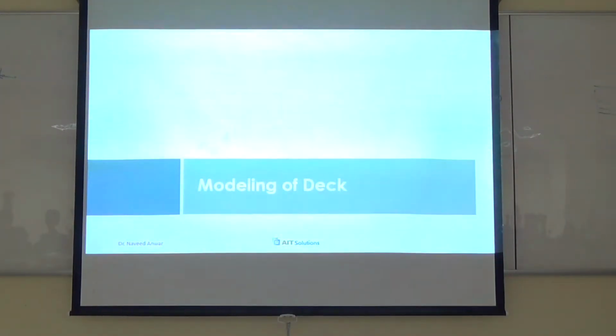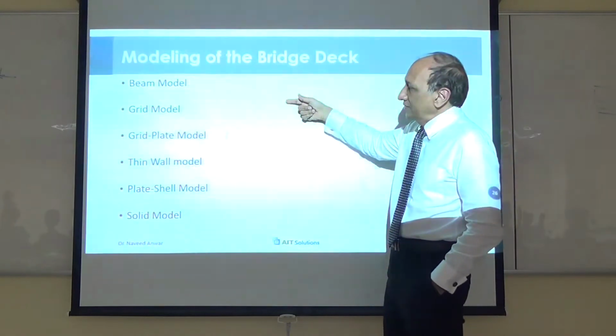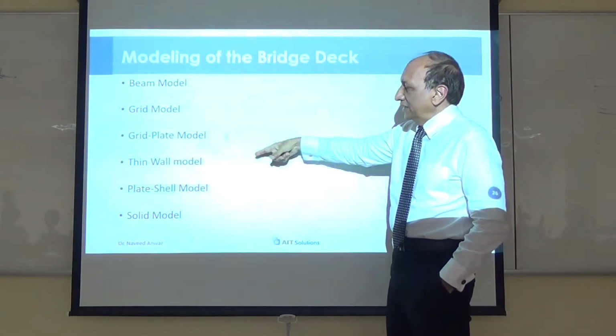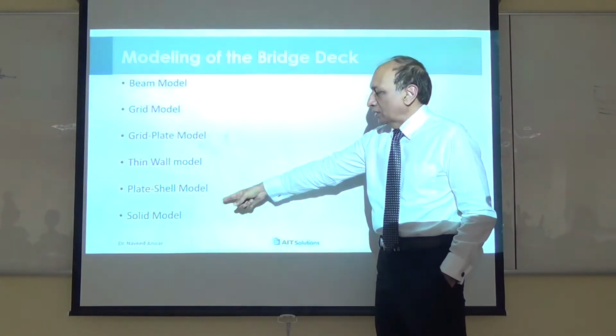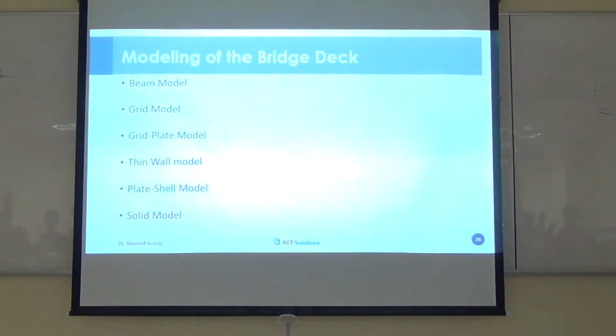So let's go back to now a little bit more details on how we model the deck. So that's the overall concept, how we model the whole bridge. The deck itself can be modeled as a beam element, grid plate model, thin wall model, plate shell model, or solid model. So you can have all these models. And the thesis that I mentioned to you, she basically studied all these models on a bridge and see which one is the best one.